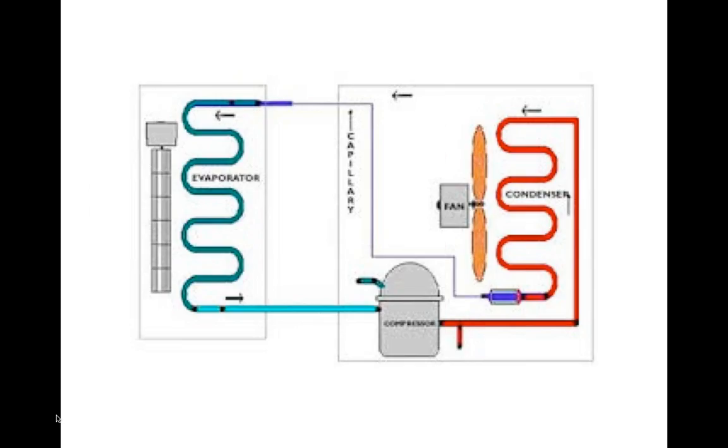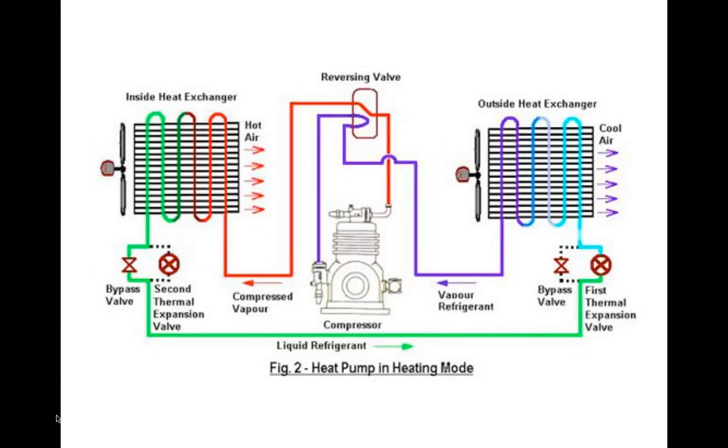Okay, and many of the operations that we see for cooling, even in giant buildings, work very much like this, except that in a giant building, instead of the evaporator having a fan blowing over it, it might be sitting inside of a large shell and tube device, where it's actually not cooling air, but instead cooling water. And then that cold water is piped all over the building, so it can be pumped through coils that you blow air over locally, and cool the air that way. On the other hand, there are many buildings that use giant evaporator coils, just blow air over them and then duct the air all over the building. So you're going to find that every building you go into is going to be slightly different. Okay, so that's how that works.